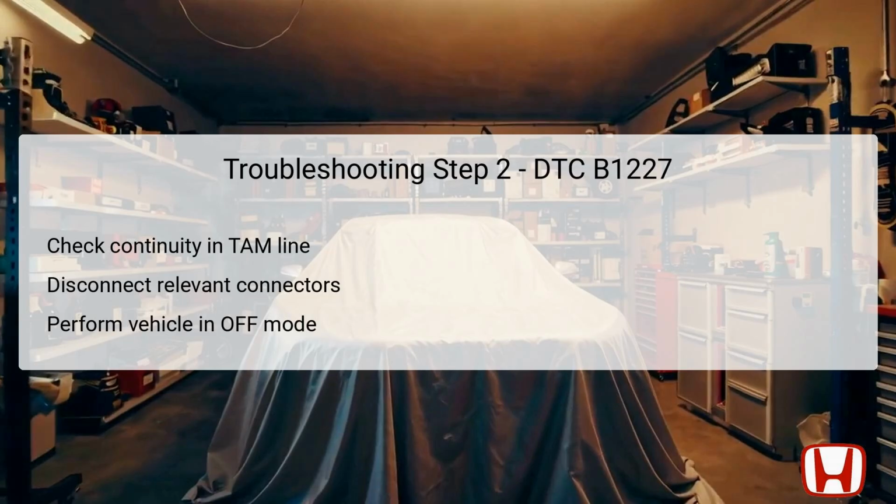This test confirms if there's a continuous wire connection without breaks. Ensure the vehicle remains off during this process. If continuity is confirmed, it indicates that the TAM wiring is intact, and attention must shift to further troubleshooting steps.